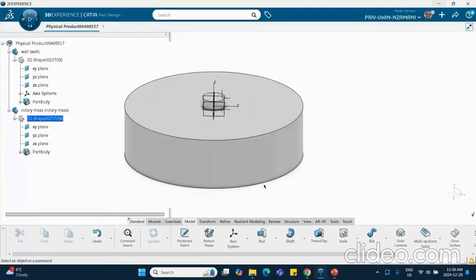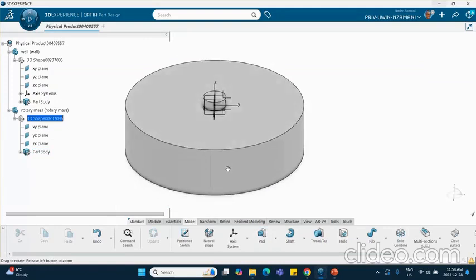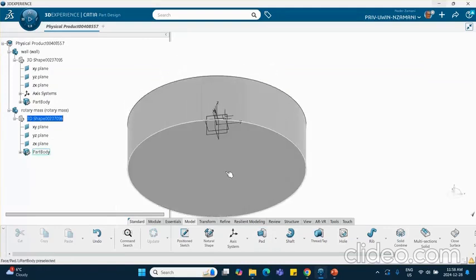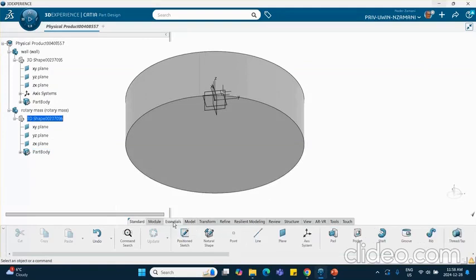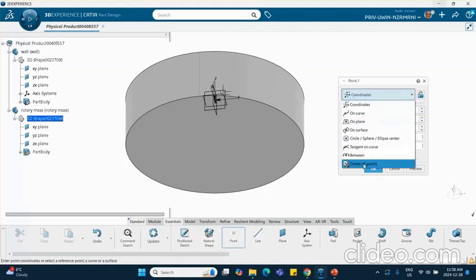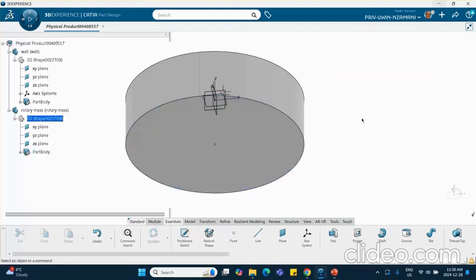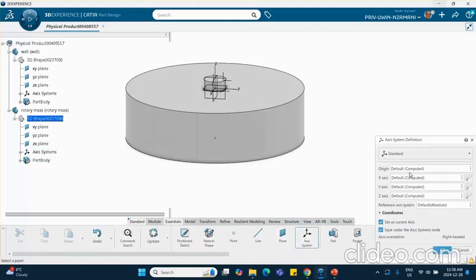Okay, now let me create an axis system, but so that I can see things easier, I'm going to create a point down here and put the axis system down below. So let's go ahead and make a point here in the middle of that bottom piece, right there. And now when I create my axis system, I'm going to put it down there. The origin of it I can pick, and I'm going to pick it to be there so that I can distinguish it from the thing up there.